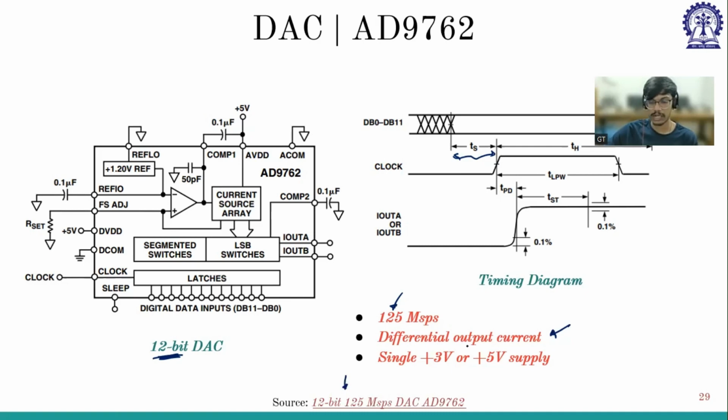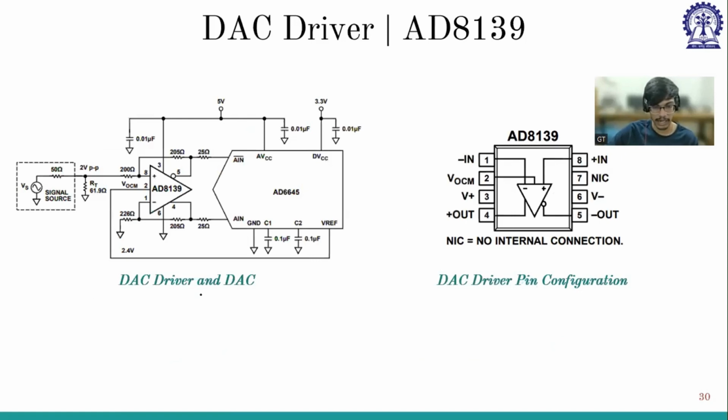So it is in differential. Again, I want it to be single-ended, so I'll use another DAC driver. This is my DAC, and it is going into the DAC driver, and my output is coming over here.